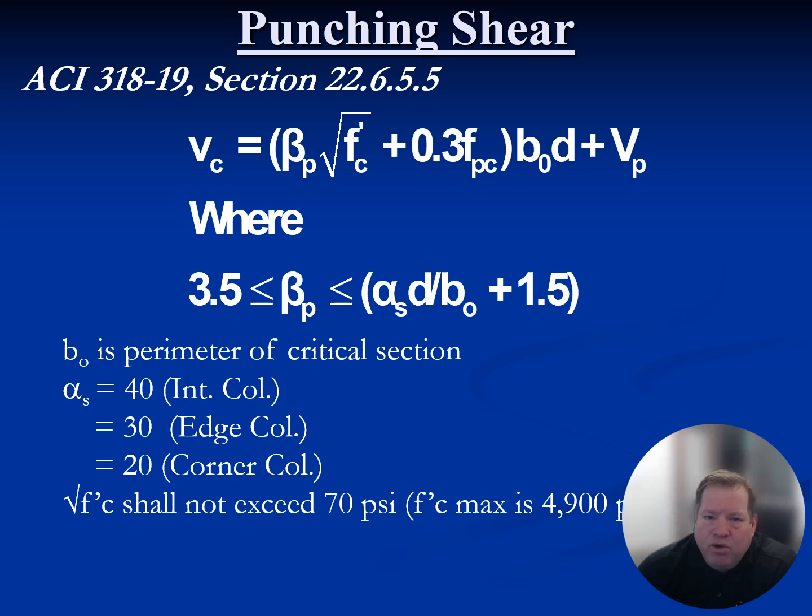Now, having said that, you can use 6, 7, 8,000 psi concrete in your slab designs. It will benefit you in stresses and strength in terms of flexure, but you're not going to get anything out of it for punching. Why? I don't understand it. We've tried to change it because you can use 6, 7,000 psi in rebar concrete.